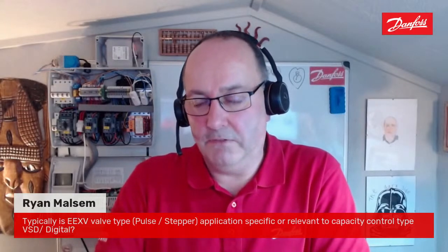If you then have a VSD drive on there that is controlled by suction pressure, then you have the possibility that your VSD drive will speed up and slow down as that suction pressure moves backwards and forwards. You can slow down the control of the VSD so that it smooths that out a little bit. But personally, if it's a one-to-one, I would always go stepper. If it's a supermarket installation, for example, or 3-4 display cases, no problem with a pulse whatsoever. So that's the simple answer, if you like, but maybe that's a topic for another day.